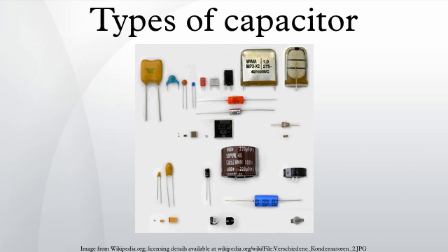In many applications of capacitors, dielectric absorption is not a problem, but in some applications, such as long-time constant integrators, sample and hold circuits, switched capacitor analog to digital converters, and very low distortion filters, it is important that the capacitor does not recover a residual charge after full discharge, and capacitors with low absorption are specified.